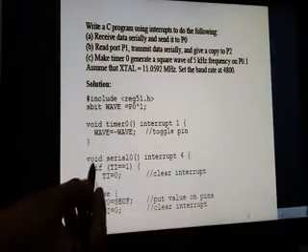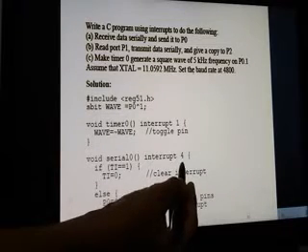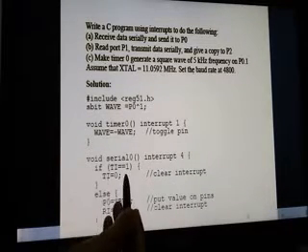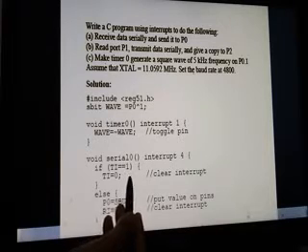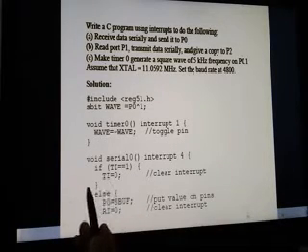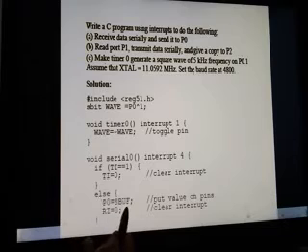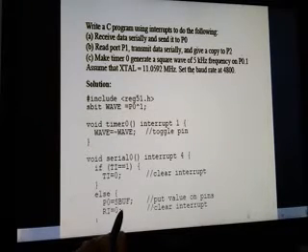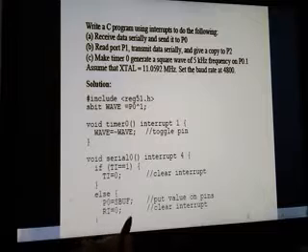Serial function, what do we have to do? Interrupt number 4. If transmit interrupt flag TI is equal to 1, then make TI 0. Else, the 8051 is used as a receiver now, so the received byte is present in SBUF. Put the SBUF value to port 0 and make the receive interrupt flag RI 0. These are the two functions.